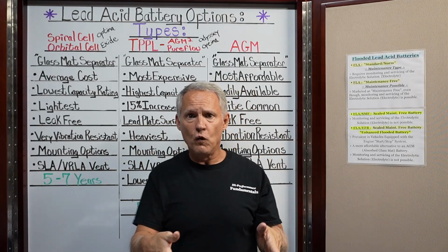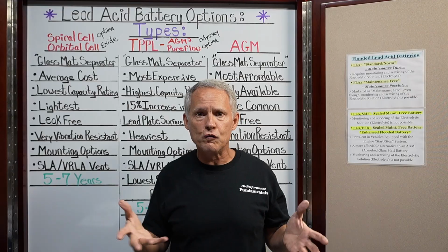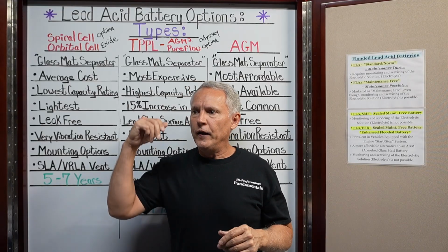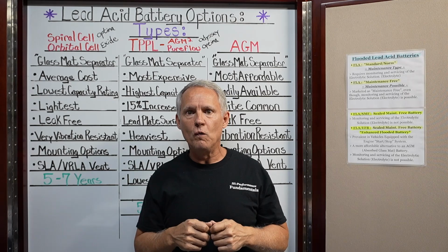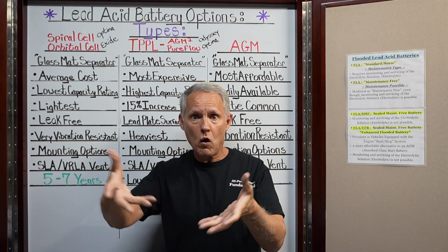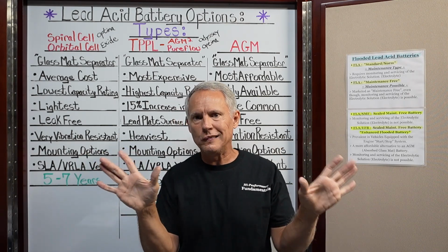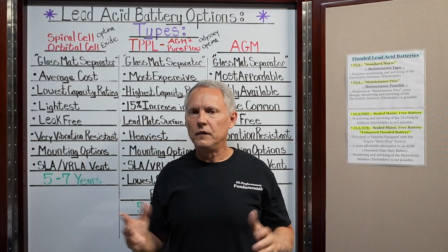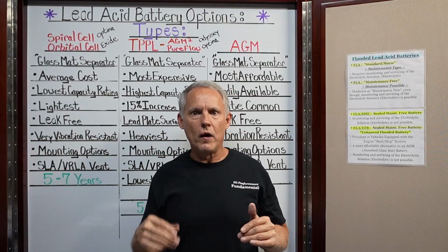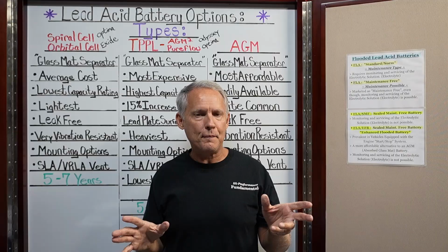So if you put a 16 volt battery in a standard passenger car, truck, or what have you, or boat, and you put in an adjustable alternator, or one designed to charge a 16 volt battery, let's say you just buy a 16 volt alternator, it's designed for that, it's not adjustable necessarily, right? Then all of a sudden it gets up and charging, things start going haywire. The car doesn't act right, starts shutting down, weird stuff can happen.